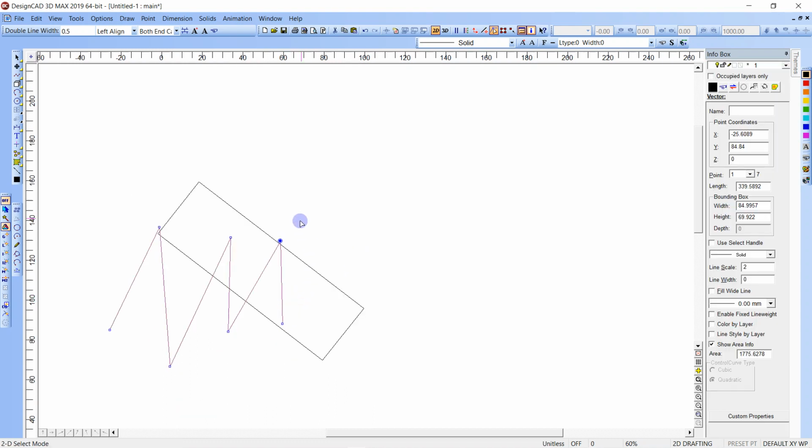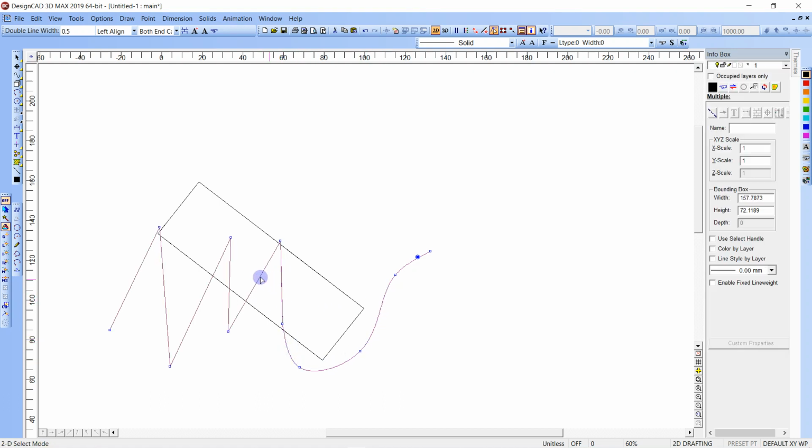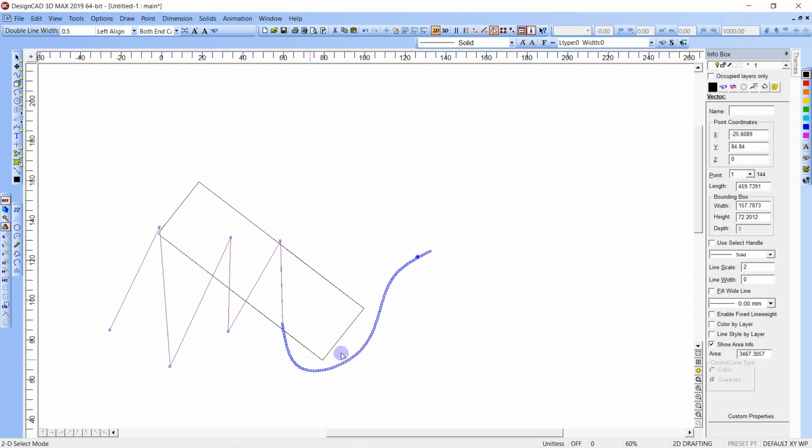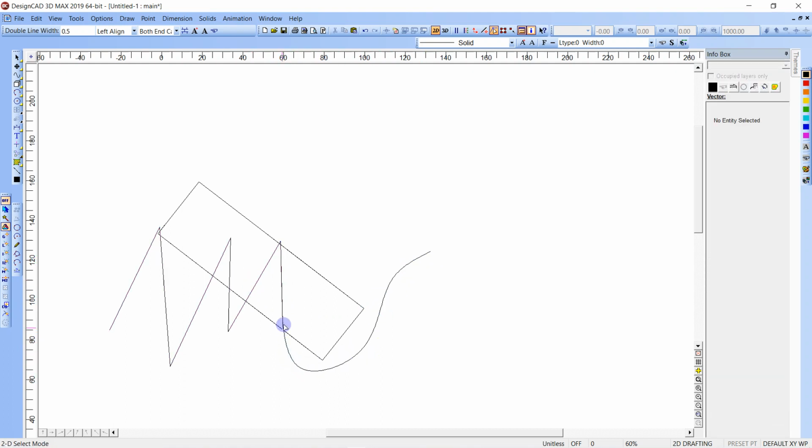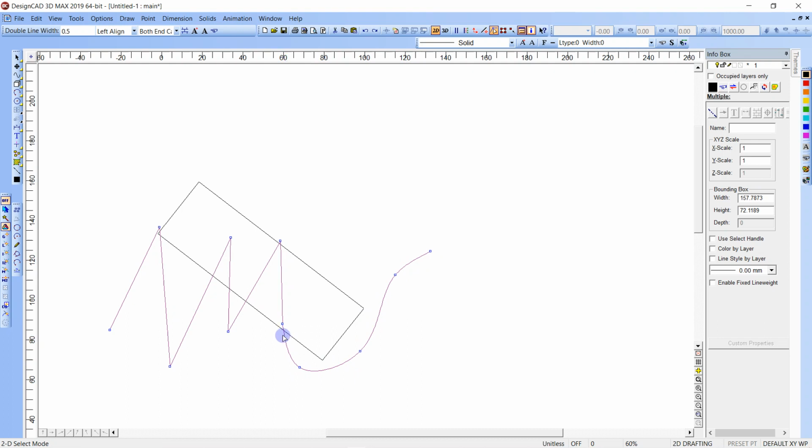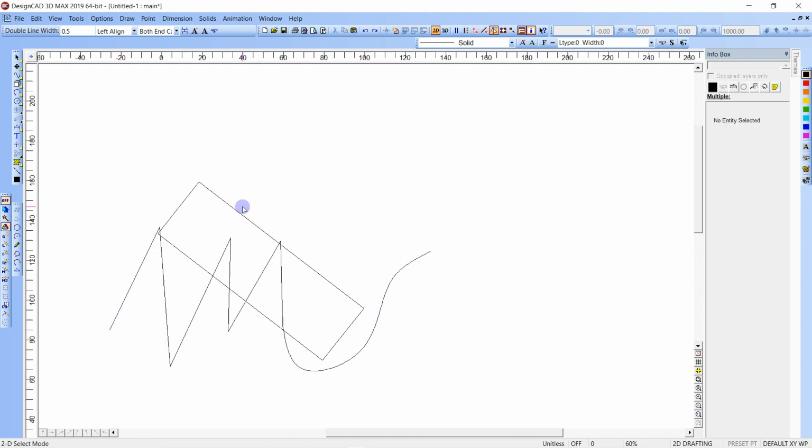If you have a curve on the end, let's go like this. The shortcut key for curve is C. So if I hit that, see it's a curved line. It's got control points on it along the line. Select them both, and if I hit B, it'll vector convert that line, and then Control Z. Let's say I wanted to do a double line, hit equal sign, and I just select the distance off of there.